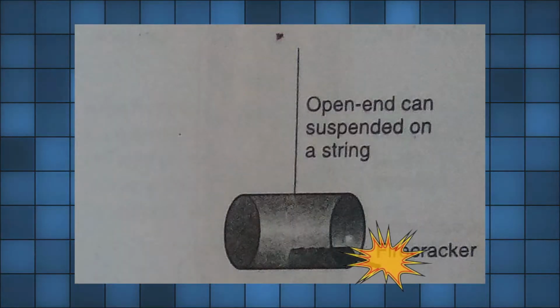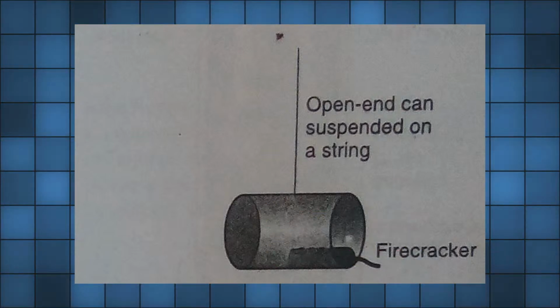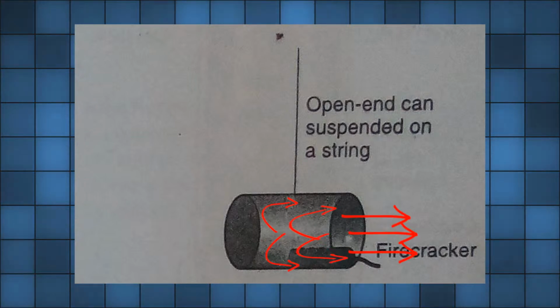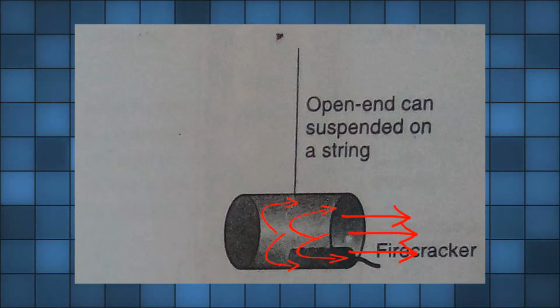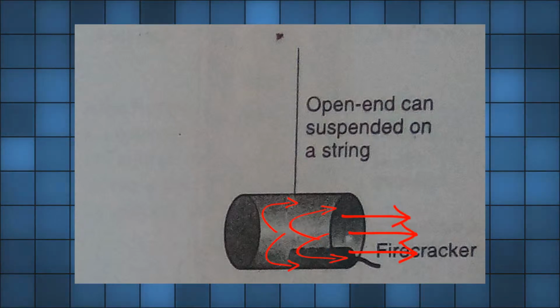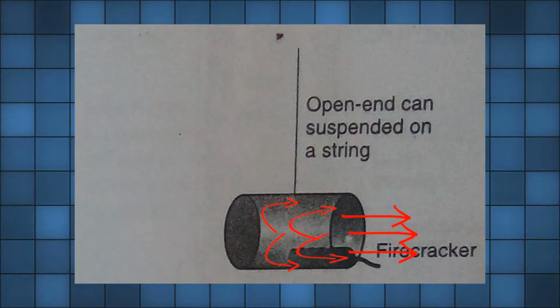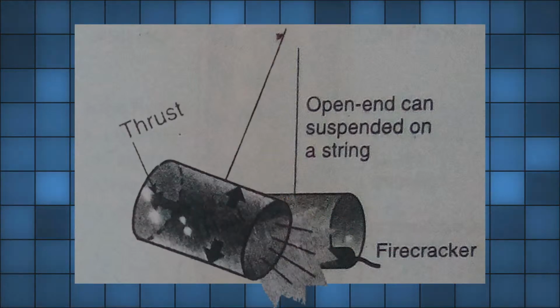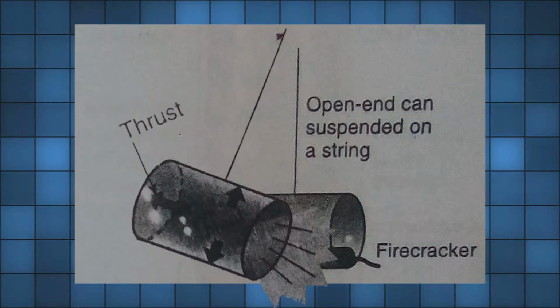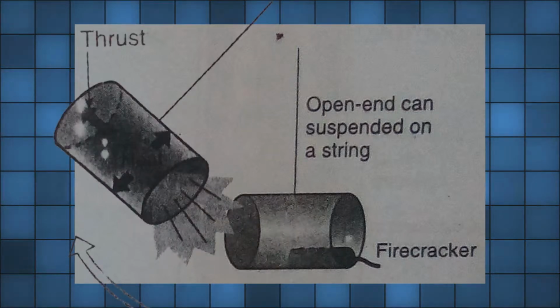Aircraft turbines. The jet propulsion principle can be explained through a tin can with a firecracker. When the firecracker is ignited, the air inside the can is heated, and it expands uniformly and produces a force in all directions. The forces that act on the can's side walls cancel each other out, since the gases are free to escape from the open end. A force is produced that acts on the closed end of the can. This force is called thrust, and it is caused by the acceleration of air leaving the can. This thrust causes the can to swing violently.